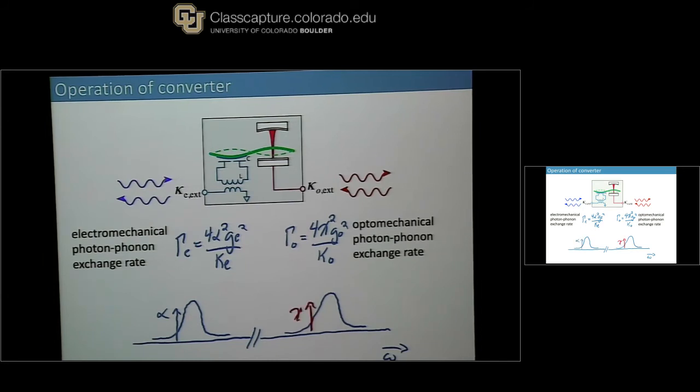And then what we want to do is end up transducing some small fluctuation that occurs sort of as a sideband with respect to each of those guys. Okay? Classically, I can think of this as sort of I put another tone in there, and then there's the amplitude modulation in the cavity, and then that drives the mechanical element a little bit, and then I read that out over here as a sideband. Okay, that's the sort of hand wavy argument.